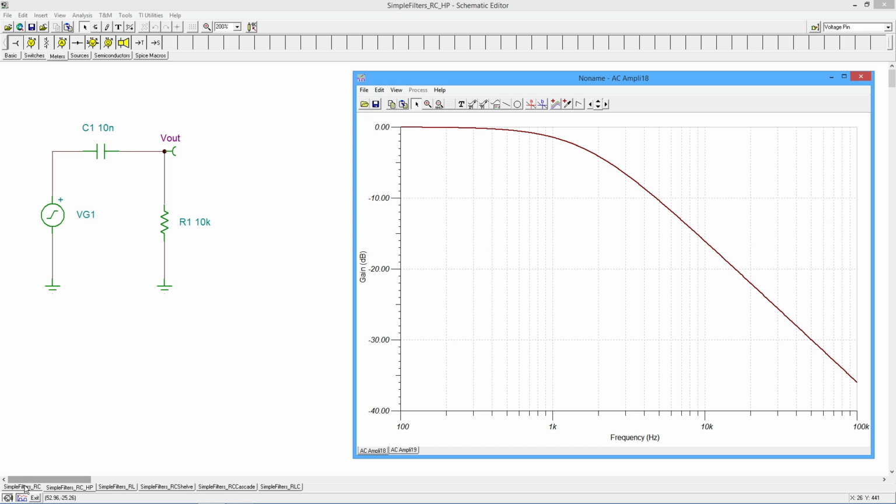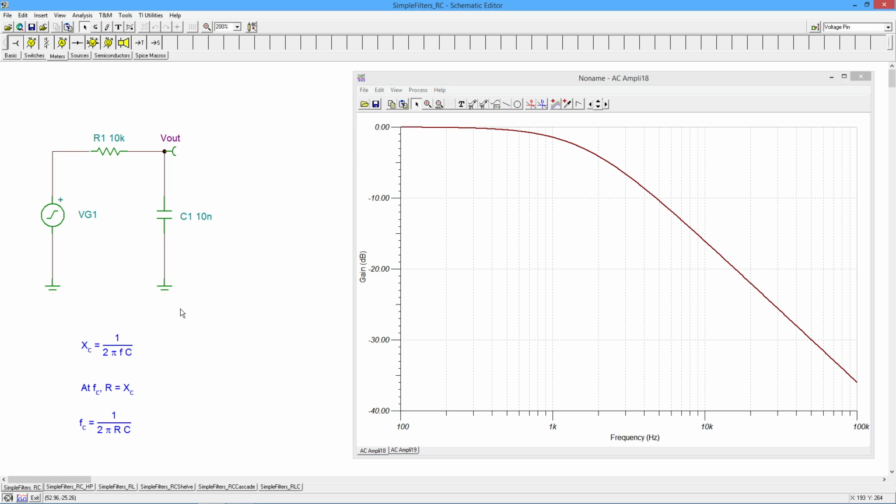In other words, this guy right there, the original one. You can do this with an inductor. Basically what you do is, any of the circuits we're going to look at, which are going to be pretty much all RC kinds of circuits, you can do those with inductors. And what you do is wherever the resistors are, you replace those with inductors. Wherever the caps are, you replace those with resistors. So that would lead you to this.